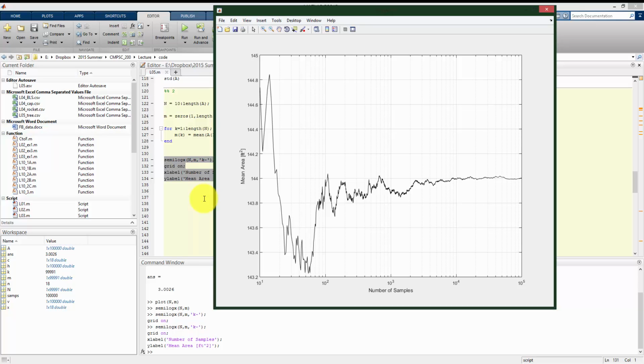But we don't want to just arbitrarily say let's use 1,000,000, because without this convergence plot, it's possible that even at 1,000,000, we still have big changes as we're adding more and more. When we see this flat line, that indicates that if we have at least that many data points, we have a converged solution, and then the estimate we're getting should be pretty good.